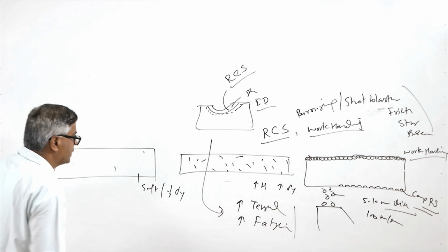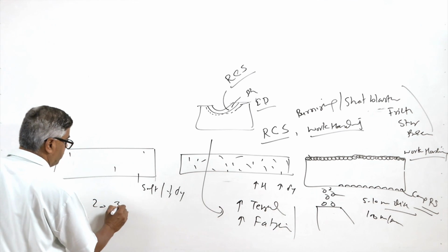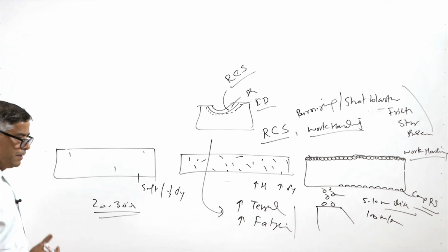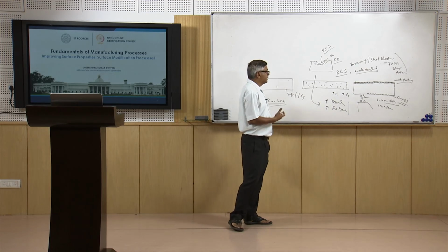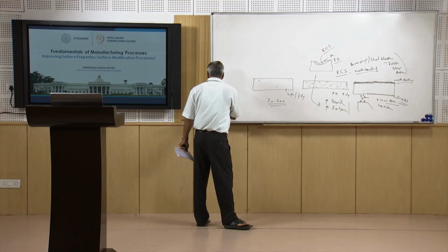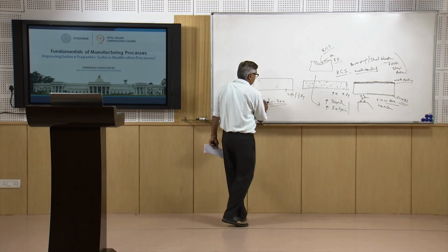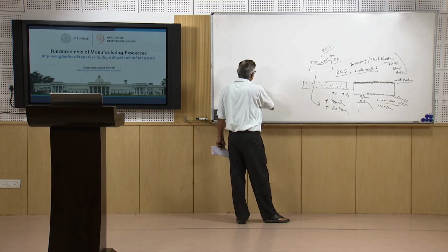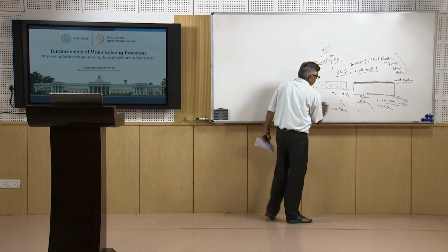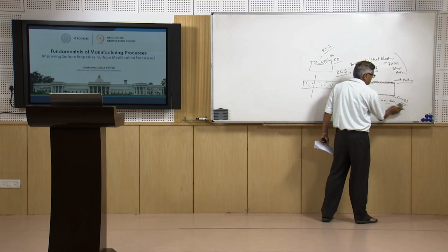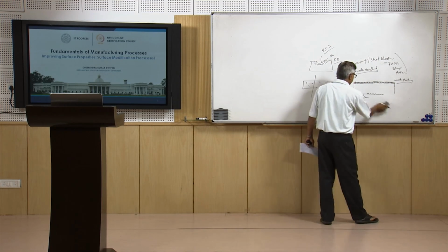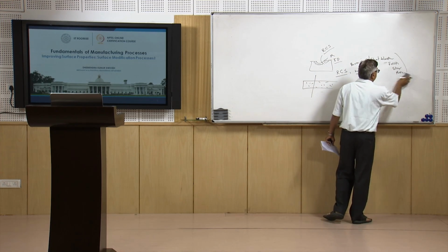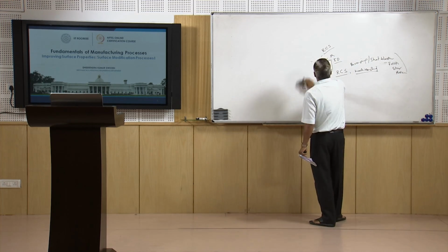It has been reported that a 20 to 30% improvement in fatigue life can be achieved through mechanical working based methods in a very controlled way, so that the surface layers are deformed plastically in a controlled way, residual compressive stresses are developed, and the surface gets hardened and strengthened, which in turn resists the plastic deformation, and the nucleation and growth of the crack required for fatigue failure of the component.